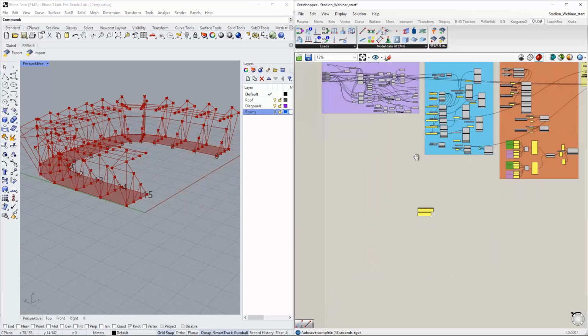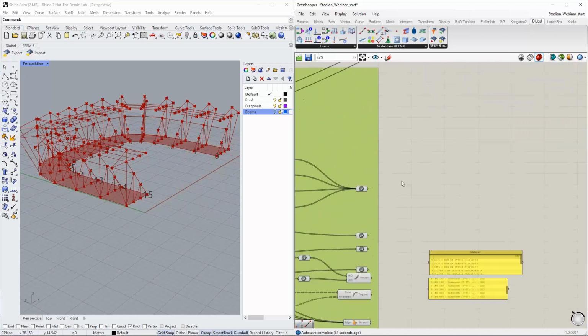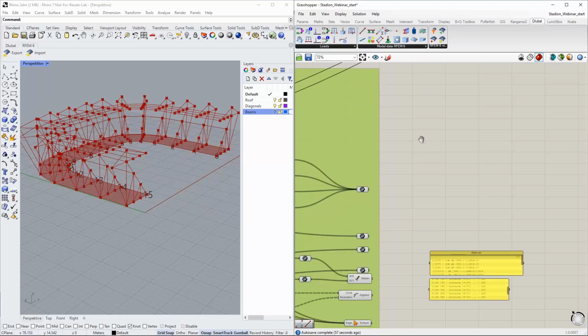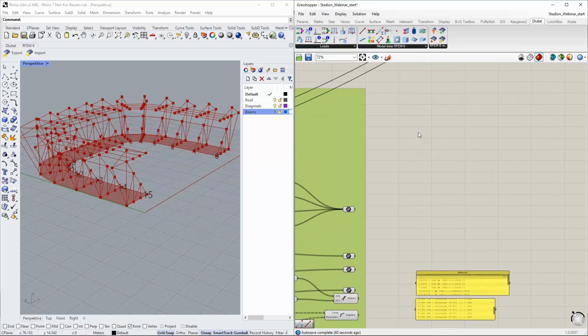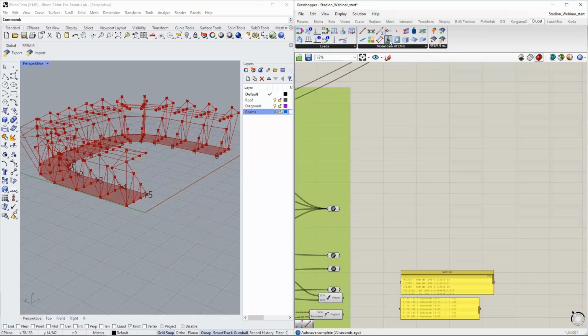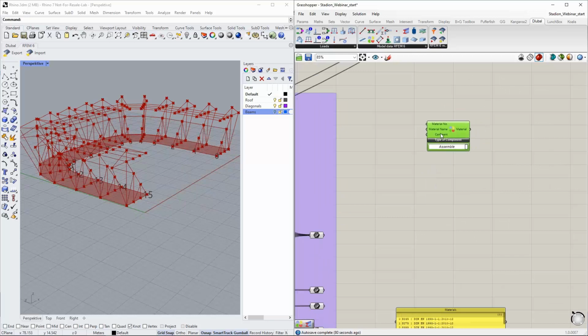So basically I will drag it down here, and let's say I would like to start with the modeling in Grasshopper for RFEM 6. How would I start? Well, for every element in RFEM 6 you need a material. It doesn't matter if it's a beam, a solid, or a surface. The material is one of the first things you have to define. So this is why I'm using here the material component. I drag it into my workspace and I will define it.